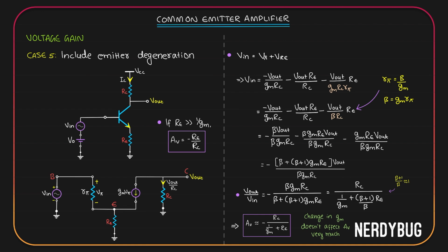Gain only depends on the resistors at the emitter and collector. But we know resistance also depends on temperature. Will that be a problem? Well, actually, no. Because here we have resistances in both the numerator and the denominator. So whatever happens to RE will also happen to RC and they will cancel each other. So we get a very stable gain because even the resistance errors cancel themselves.